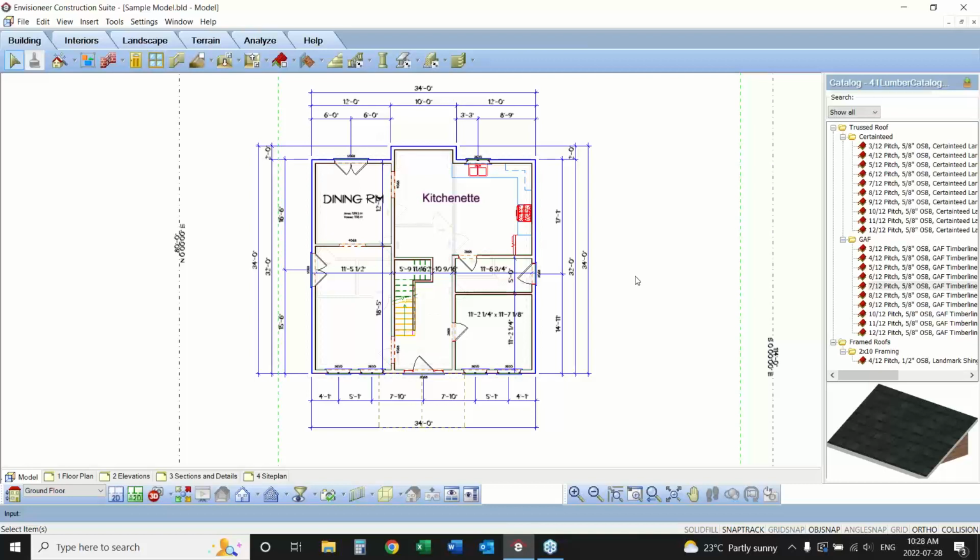The text that you add in here is always going to appear with your plan when you turn text on. So I wouldn't fully put all of my text here. I wouldn't start denoting all of my walls and putting all the text in. I would leave all of my text until I get out into the working drawing sheets, because I can then turn it on and off as I need to and put it on different layers.